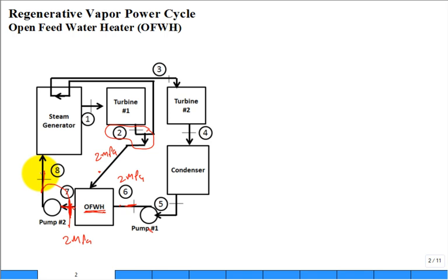So what you do is you divert a fraction. Maybe you divert 20%. Well, then what remains to continue into the process and get reheated is about 80%. And so what they do is they say, well, let this be y. What is y? Another variable. And y is that mass fraction that's diverted to the feed water heater. Okay, so y could be 20%. Then guess what is going over here? 1 minus y. Isn't 1 minus y then 80%?